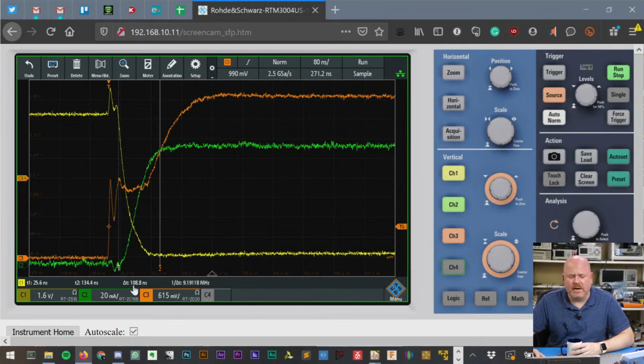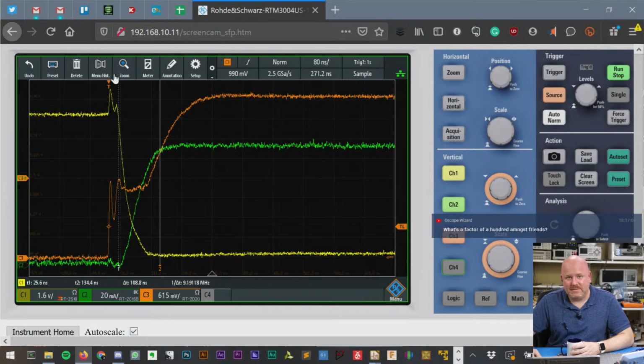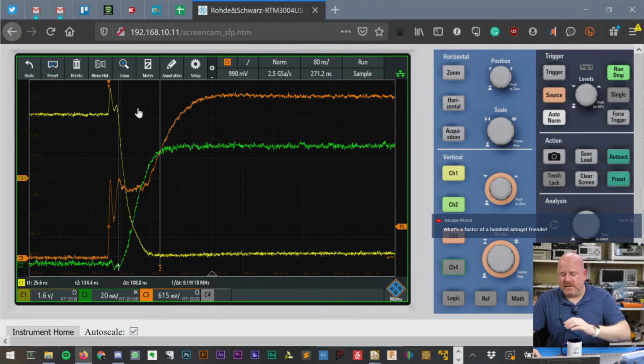So I said that wrong earlier. I thought it was 1 nanosecond, but this was 100 nanoseconds. So that's pretty fast. I mean, that's not taking very much time at all. So that's cool. But one thing I want to point out, this inductive spike is relative to how much current is going to eventually go through the channel. So the more current we could be drawing, the higher the spike, relative to the voltage we'll drop across the channel. So right now we're driving with 12 volts. As we increase voltage, this spike gets worse or bigger, and that can be bad. And I swear I had a second point and now I forgot what it was.